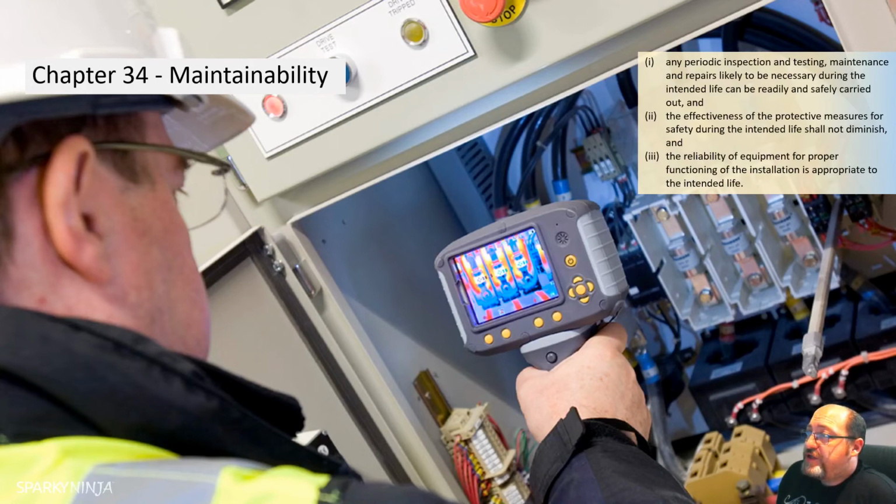The effectiveness of the protective measures used, which we'll cover in chapter 41 in the next video, will not diminish. So when we go to maintain, the protective measure for basic protection and fault protection will not be diminished. Quite often when we open an enclosure, maybe removing a barrier, maybe removing basic protection or additional protection, we need to make sure that we don't diminish the life or shorten the life or reduce the efficiency of that. And then we have the reliability of equipment for proper functioning of the installations appropriate to the intended life. So we've got to make sure that we understand the intended life and the equipment functions for that purpose.